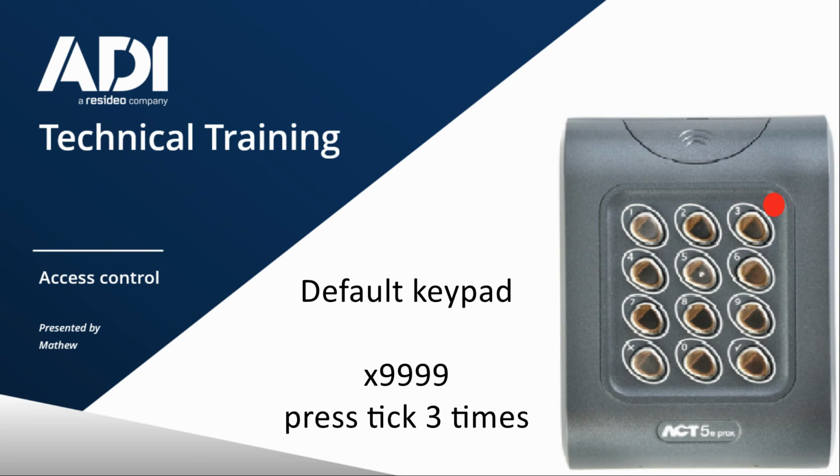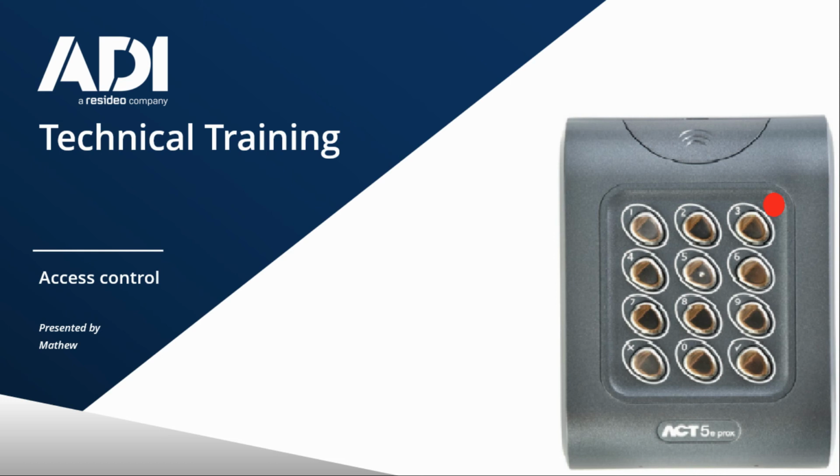So to do a factory reset, you press X, go into engineers mode, which is 4 nines, factory. And now you press the tick key 3 times. And if you listen, it will play a long tone while it clears the memory. And that's the keypad reset now. The LED goes back red. So now we have a reset keypad. And I've just confirmed that by pressing X and 4 nines.